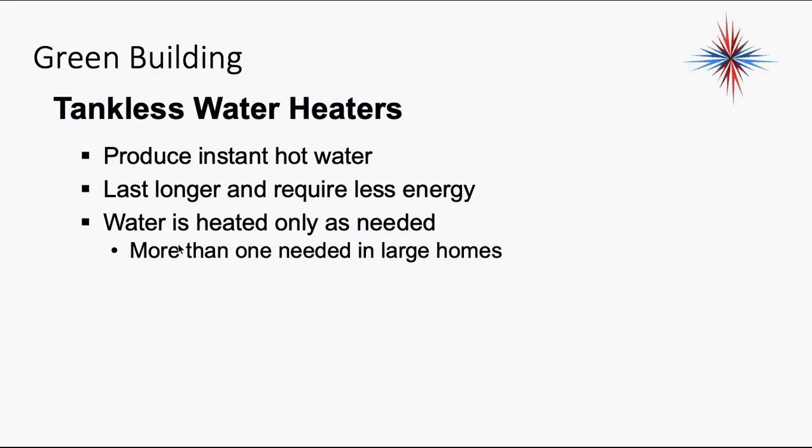Word of warning on tankless water heaters. If someone wants to install a hot tub or one of those whirlpool tubs, specifically like in the master bathroom where they have the 6-seater tub, you cannot do it on a tankless water heater. It doesn't have the capability to fill a large tub. It's meant for showers, sinks, dishwashing, and stuff like that. It just doesn't work for larger water use.